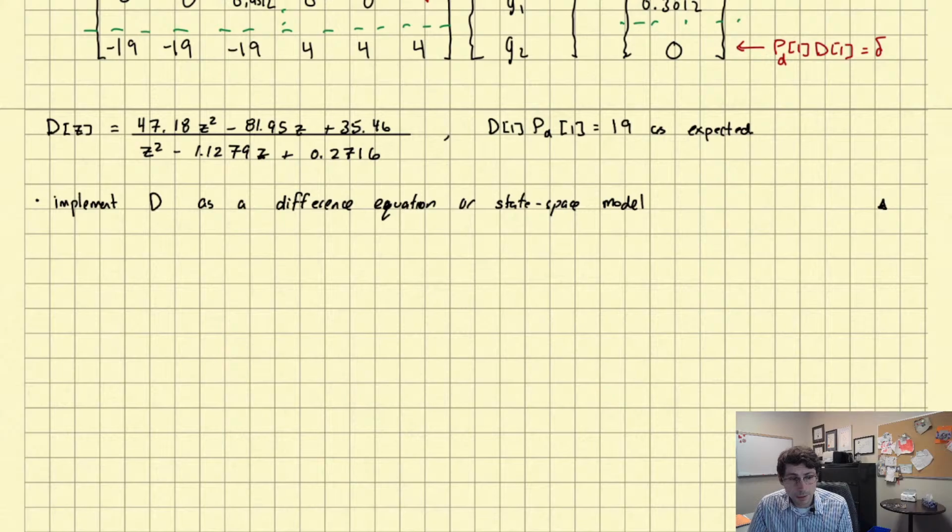Okay, so direct design pole placement. Again, it looks like we're doing the same thing. Like you say, what is the difference? The difference is we've discretized the plant. We expect there are no approximations being made. At no stage are there approximations being made. Okay, so if our plant model is very good, then when we implement it, it's going to behave exactly as we see it in simulation. I mean, of course, there'll be modeling errors, but that's a separate issue.